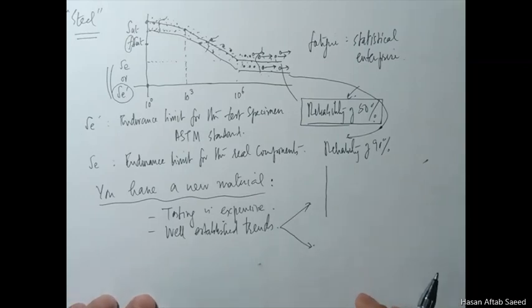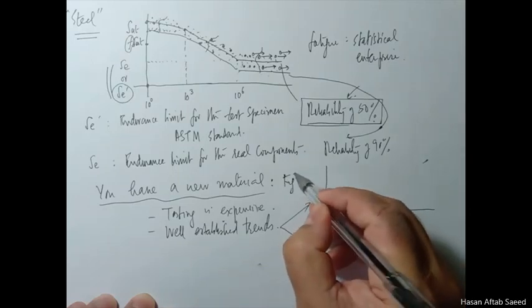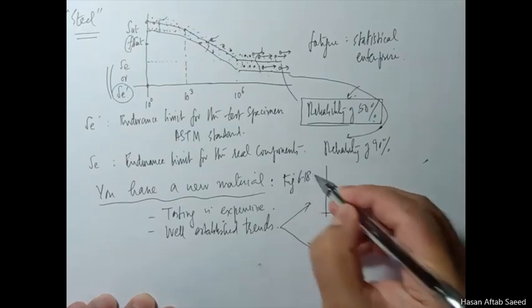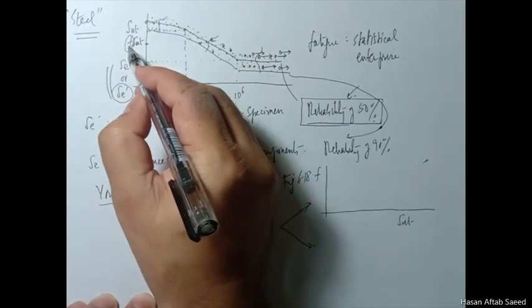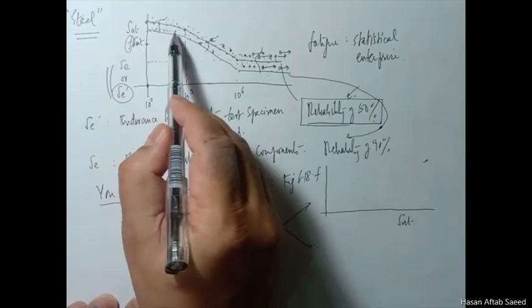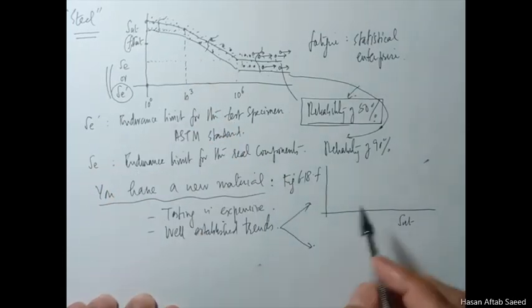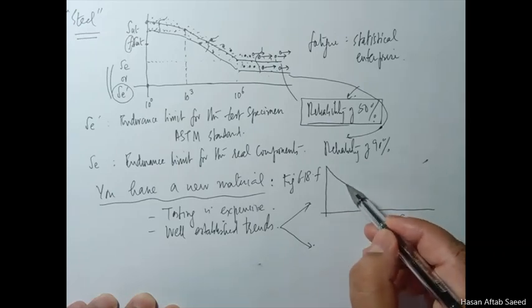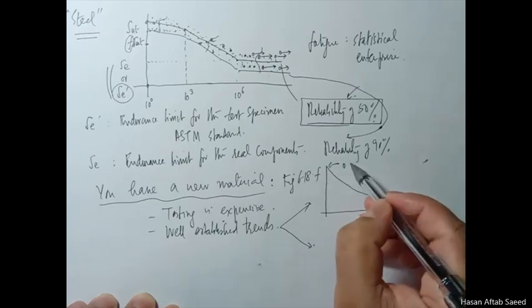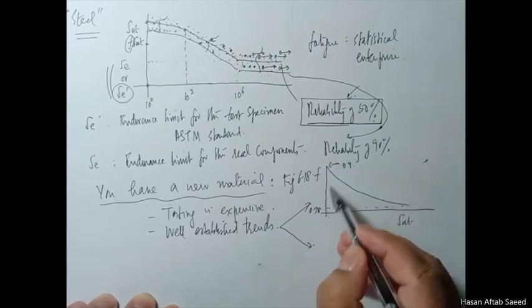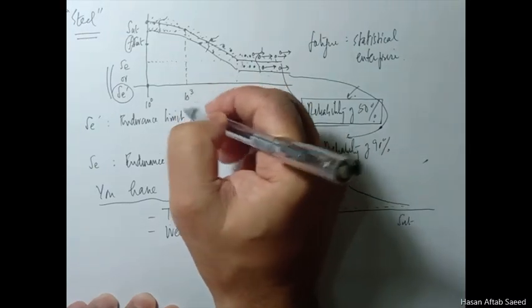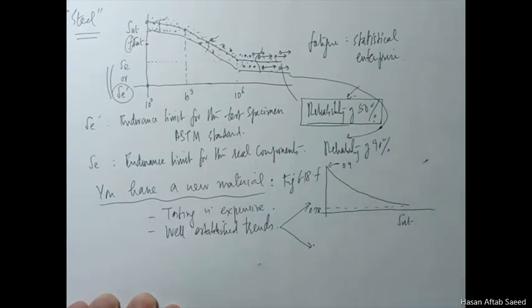So because there are certain trends, the first one, which can be found in your textbook, is figure 6-18. It basically gives you the relationship between the ultimate tensile strength and this fraction, by which the strength has been reduced after 1000 cycles. It is something like this point is 0.9, and the lowest point is something about 0.78. So this much strength has been reduced by the time 1000 revolutions have been completed.